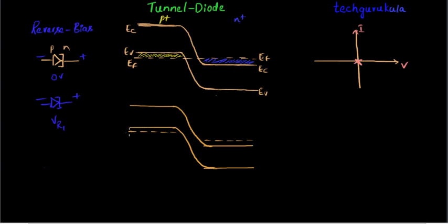So now the quasi-Fermi level at the P side will be at a higher level. The energy states of the holes are represented in yellow, and the filled electron energy states on the N side are represented with blue color. Now you have a lot of minority electrons here, and we have seen what tunneling is before, when we discussed the forward biasing of the tunnel diode. Now if we consider the electrons here, there are vacant states above this quasi-Fermi level EFN.